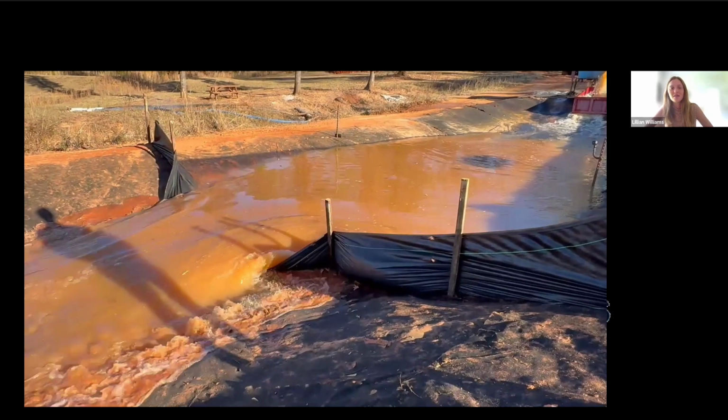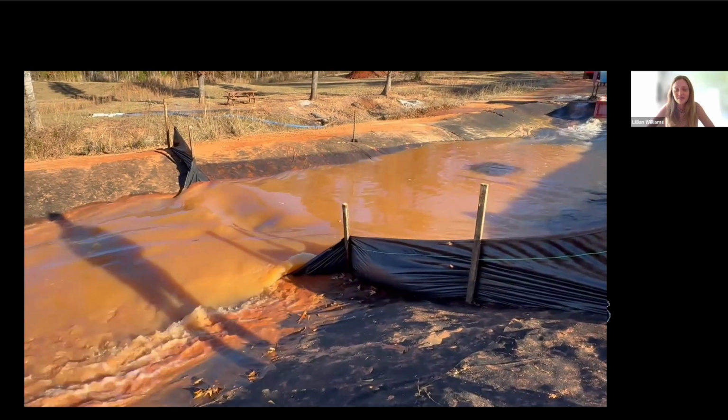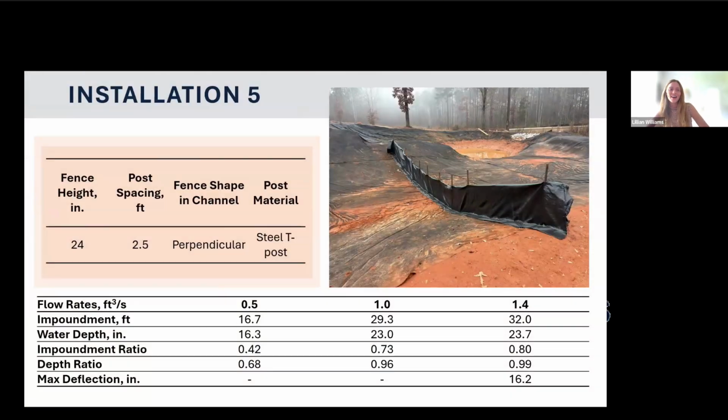Last video, I promise. But I just think it's so neat to see it fail, which also means that I could stop testing at that time, so it was great. Installation 5 was a 24-inch height and 2.5-foot post spacing, so we changed both of those, and that was a combination of installation 1 and installation 2 for a possible MFEI. There was still quite a bit of deflection, however, structurally it performed a lot better with the zip ties not ripping through the fence, and then the impoundment ratios were pretty high as well.